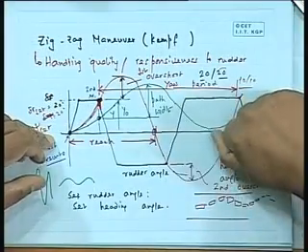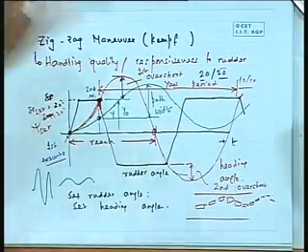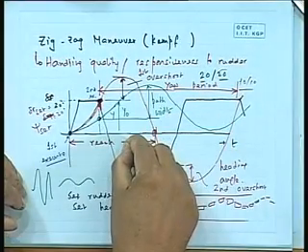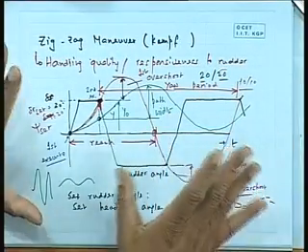So this reach will come down, the full thing will get stretched this side, as if you are holding and stretching this graph, if the ship is directionally stable and rudder effectiveness is less. On the other hand, if the ship is directionally less stable and rudder effectiveness is very high, then this gets squished back. So it will overshoot more but turn faster. This is what the general feeling is. I am not writing it down, but generally this is the case.